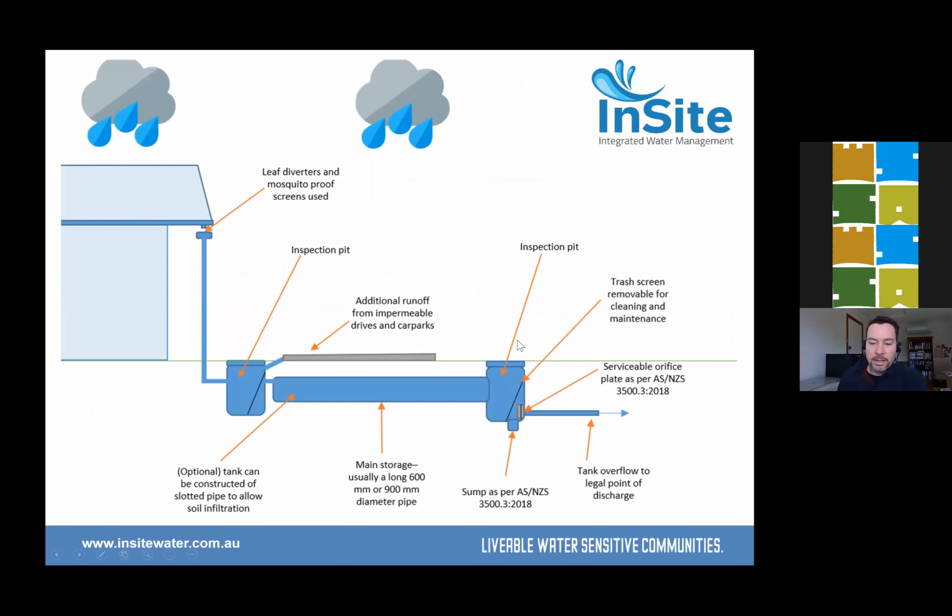Now, I don't think you saw this one, so this is a simplified diagram of what I'd call a traditional on-site detention pit. It's not encouraged under the new Australian Rainfall and Runoff Guide because it does only meet one of our 4 criteria. It doesn't harvest or infiltrate water or improve water quality, but it is a useful tool for managing peak flow rates, and you can very specifically create an orifice and a specific permissible site discharge flow rate out of the orifice.